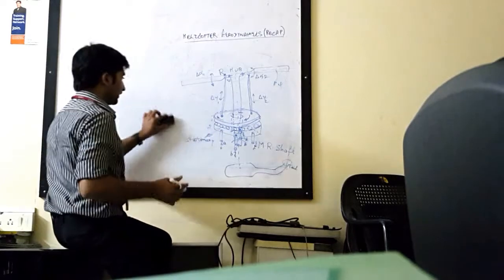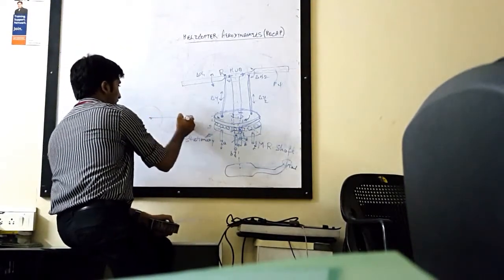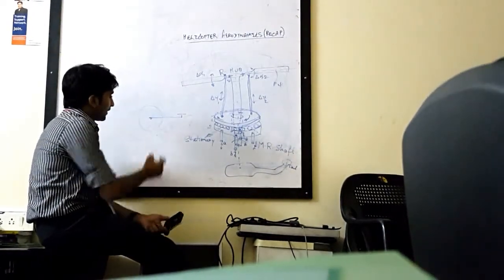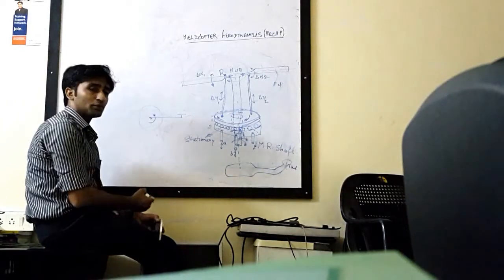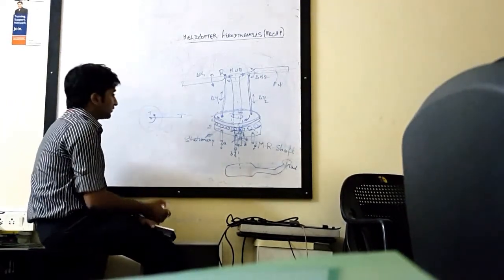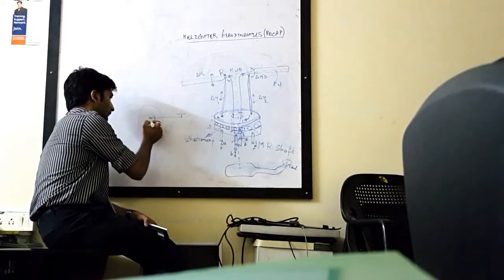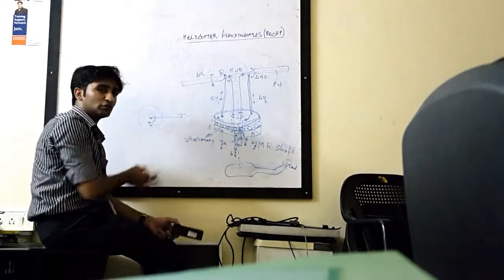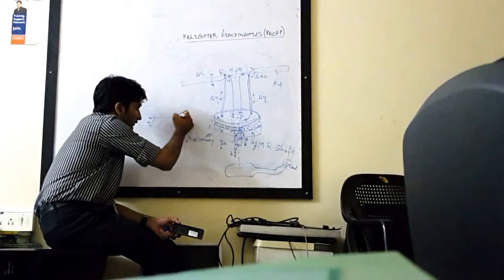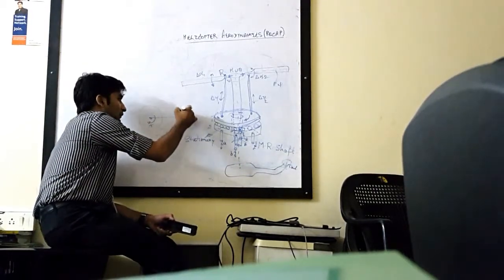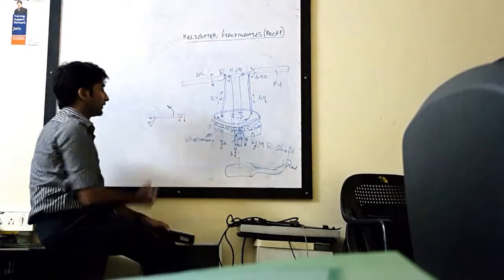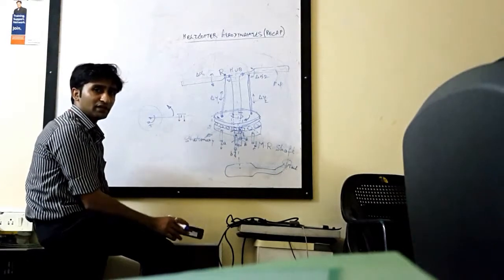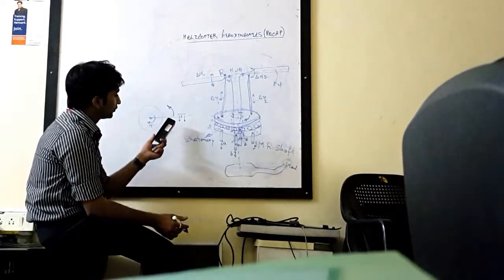Looking from the vertical direction, what you have is a main rotor disc and a tail rotor disc and you have a tail rotor, right? So now in this case, there is a torque being produced because the helicopter rotor is moving. Let's say that is the torque, and it tries to rotate the helicopter like that. So what you do, you put an anti-torque. Now this will produce a negative moment by which the helicopter will stay stable and level about the x-axis. So now what if you want to change the yaw?